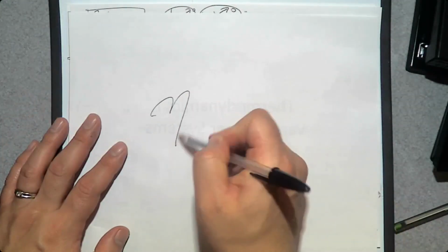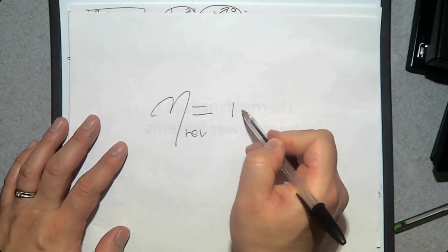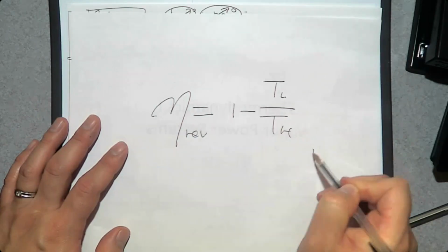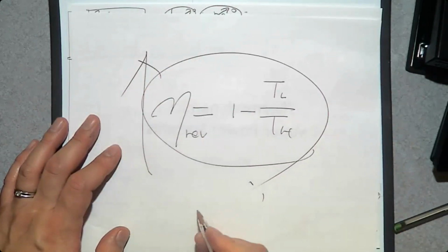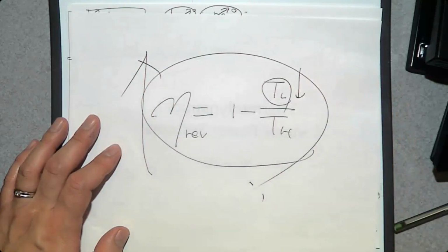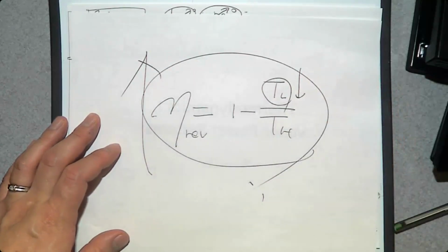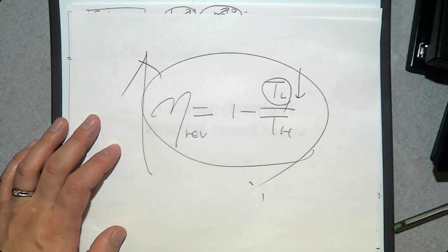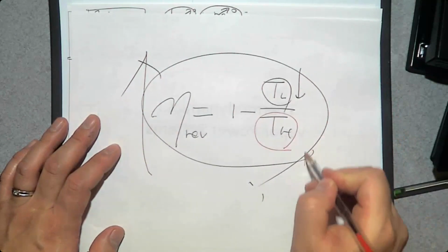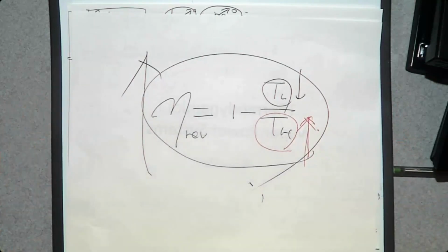If you remember, the thermodynamic efficiency, which is the Carnot efficiency, is 1 minus TL over TH. You remember that. To increase this value, what can you do? Decrease the temperature of the coolant. We don't want that to happen, right? Climate change. So the only way is to increase the temperature of the source. How can you increase the temperature of the source? It's very simple. You just need to replace water with another material that has a higher maximum temperature.